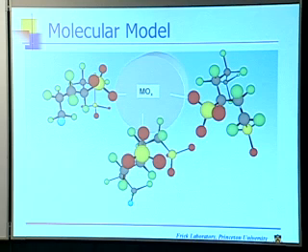The question is, is there enough metal oxide in there so that you have surface sites that can tie up all of the sulfonic acids? And remember, those sulfonic acids are critical to proton transport, so if you tied them all up, you'd have a very poor material. Second of all, there simply aren't enough based on the masses that are available. What we believe is happening at 300 degrees or a little higher than that is there's enough mobility in the polymer that we're getting a lot of sulfonic acids sampling the titania surface in a relatively short time.